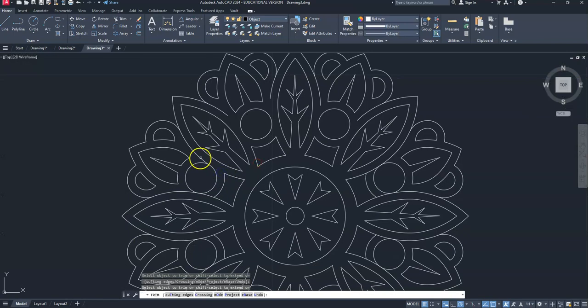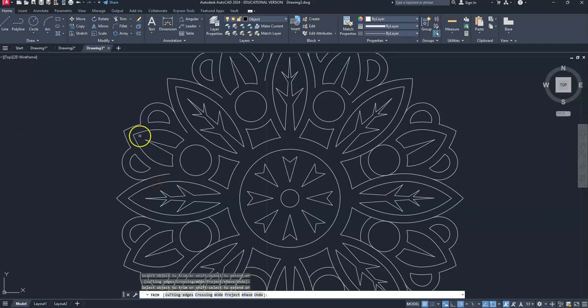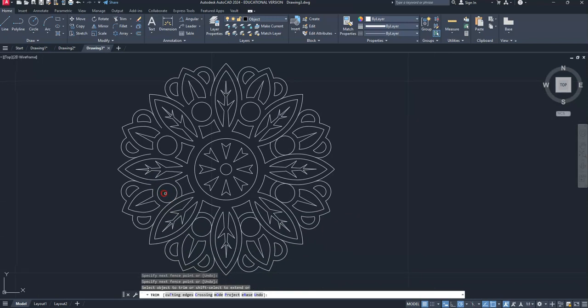But you do need to make sure there is no line here, because if that line is there, the laser is going to cut that, and then there's going to be nothing holding it on. So notice this shape has a solid line. So this shape here is going to be removed totally from the material. It will not stay. It's not going to be attached in any way.